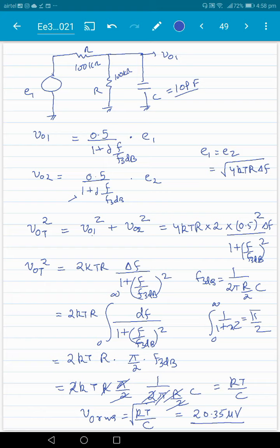Right, so what we have shown here is that in circuits, resistors are a source of noise, diodes, transistors, MOSFETs, bipolar, are all a source of noise, and op-amps are a source of noise, obviously. So you can calculate the net noise present at the output by propagating the effects of the noise due to each component. And you can also take the net noise at the output and divide it by the gain, and convert that into input referred noise also. All right, so noise